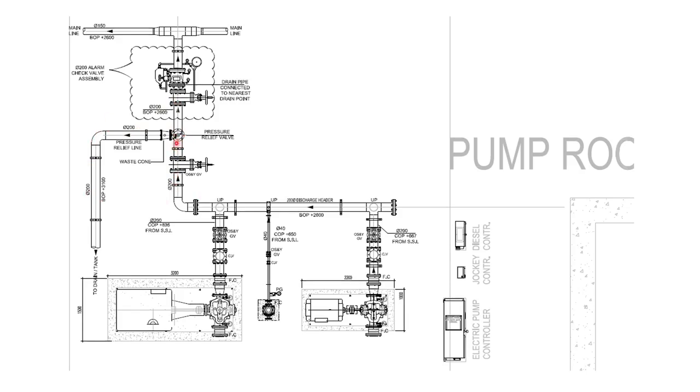Please note, this might not be accurate, and as per NFPA 20 we need to consider the pressure relief line before this check valve. For electric fire pumps there is no need to consider this overpressure relief line.